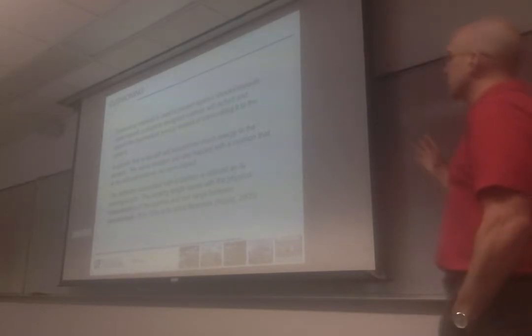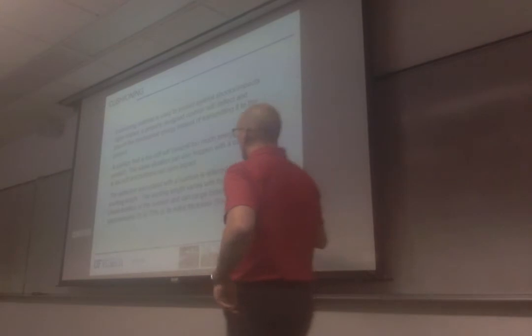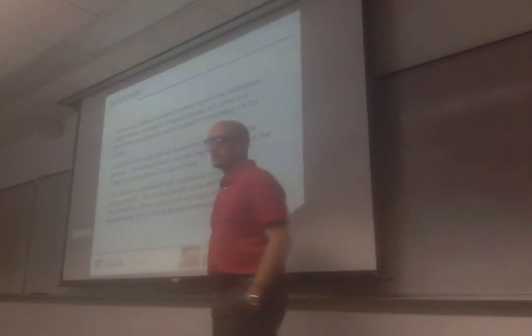If the cushion is too stiff, it will transmit too much energy to the product, and the same situation can happen if the cushion is too soft, because in this case, it's going to deform so much that it's going to exceed its working length, and you're going to have the product bottom out, right here. So that is an issue as well.